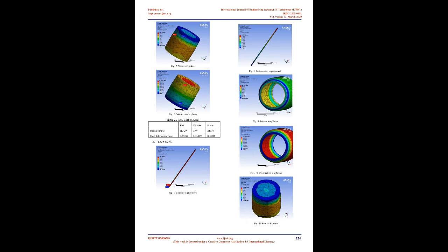Design of the piston. Let A be the full area of the piston and a be the cross-sectional area of the piston rod. Since the design is a double-acting double-ended hydraulic cylinder, pressure is exerted on both sides of the rod, hence the area on which the pressure is acting is given by A minus a. The force produced is given in the equation below. From the BAME Hydraulics Corporation Catalog of Metric Rod Wipers and Piston Seals, the nearest standard diameter is 100 mm.